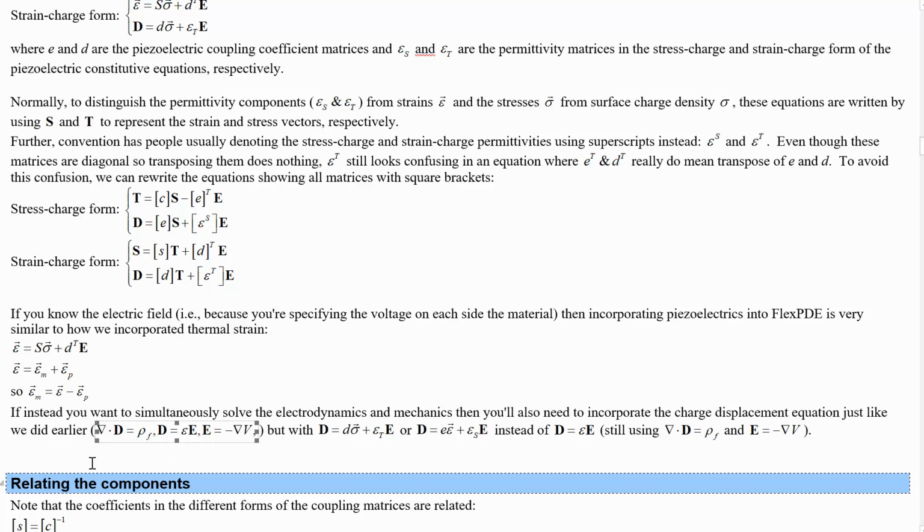Within dielectrics, which are piezoelectrics, you generally don't have free charge density, so we'll be okay to say div of D is equal to 0, except possibly in the contacts around the material. So at the boundary, we could have D coming in from the outside, but there's no divergence of D within the material.